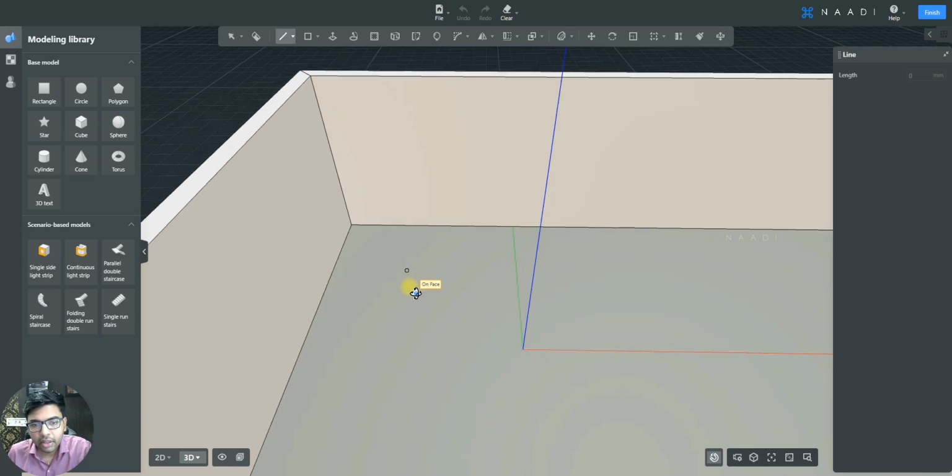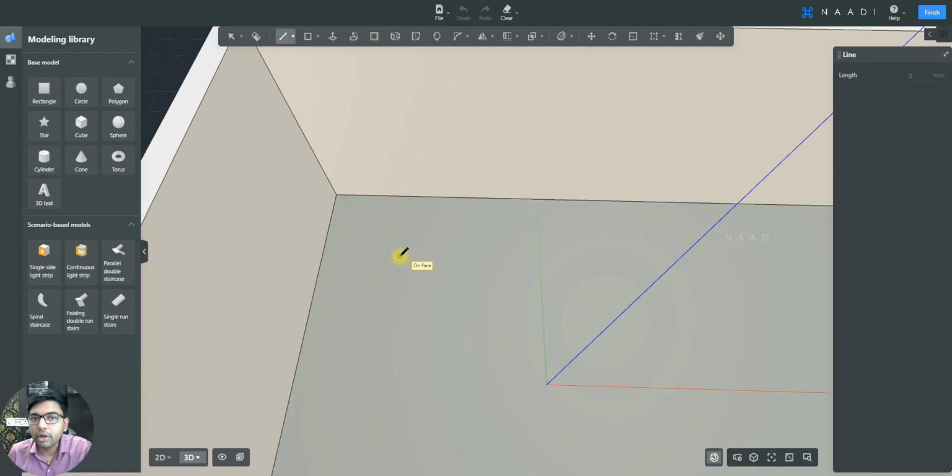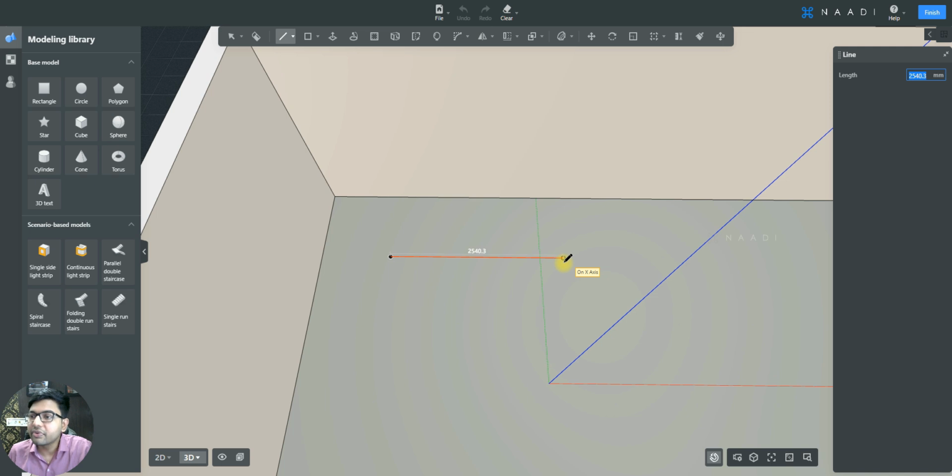Shortcut is here. If you click it, just like your conventional modeling, you can draw a line here. So you can just click on the starting point and then you can take your cursor based on which the line will be created. Can you see here? And in any geometry creation process in custom modeling, you will see 3 different axes here, which are your X, Y and Z axis, where your X axis will be in green color, what you're seeing, and your Y axis will be in red color and your Z axis will be in blue color. And if you align your geometries in that specific axis, the edge color of the geometry will also be in the same color. So if I'm drawing any line in my Y axis, it will be in red. If I draw a line in my X axis, it will turn green. Same applies for the Z too.